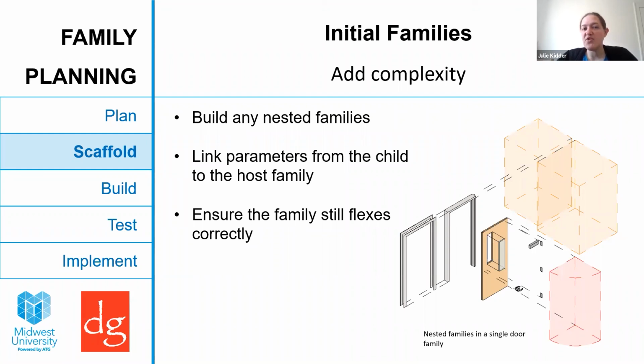How frequently do I use Dynamo in family building? I haven't used it for family building yet. I've mainly focused on using it to get information between parameters that I can't do in Revit. So I've focused more on the schedule side or on pushing information between families. I'd be interested in using it for family building if there's a way to speed that up, but that isn't something I've started with yet, and certainly wasn't where I was at in my Dynamo journey at the time I was building the families initially.